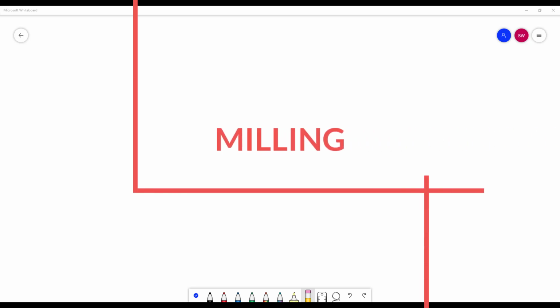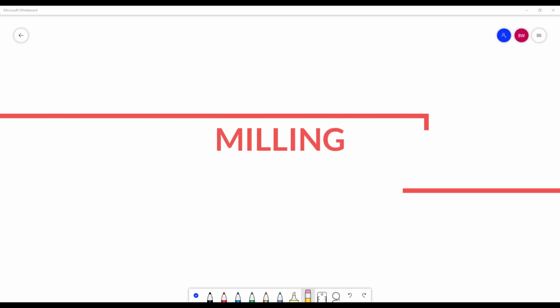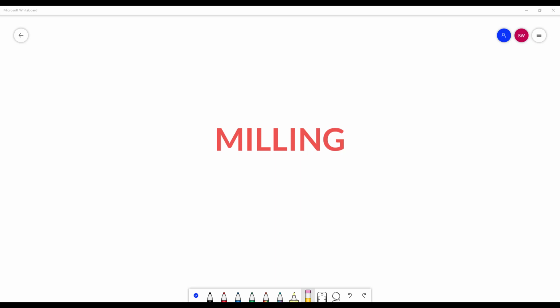Alright, so let's talk about some milling concepts here. We just did some drilling and some hand jogging to create features in the previous module. For this module, we need to worry about actually cutting. So there's a few things that are going to change. Instead of the rapid code and canned cycles, we're going to have to focus on cutting linear and circular.